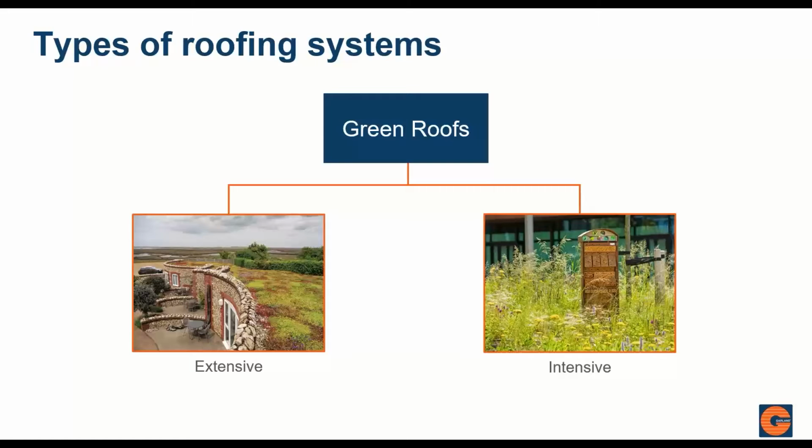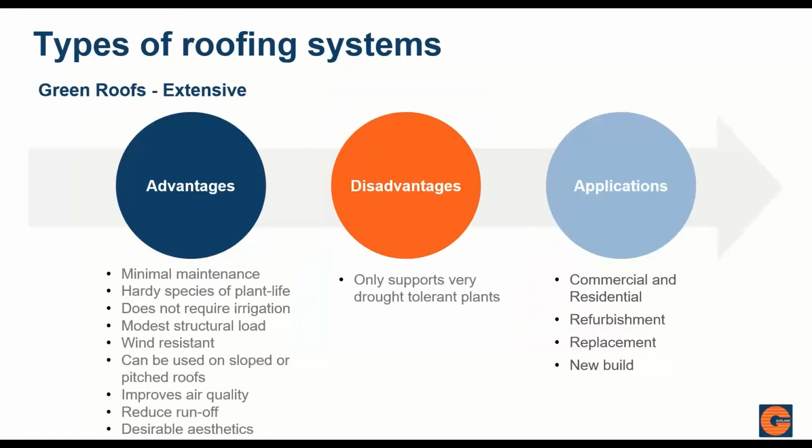And lastly, of our four systems we're looking at today is our green roofing systems. So this typically integrates a layer of green or vegetation over the waterproofing layer, and we have extensive and intensive systems out on the market currently. When we look at extensive, these are very low maintenance roofs that typically require maintenance either once or twice a year, depending on if we have a drought or if there's any invasive species that manage to establish themselves within the sedum matting on top.